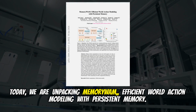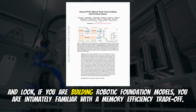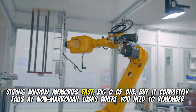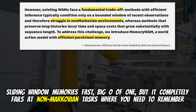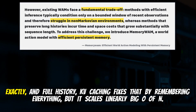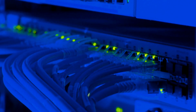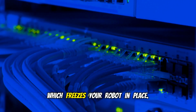Today we are unpacking MemoryWAM: efficient world action modeling with persistent memory. And look, if you are building robotic foundation models, you are intimately familiar with the memory efficiency trade-off. Sliding window memory is fast, big O of 1, but it completely fails at non-Markovian tasks where you need to remember past states. Right, because those states are not visible anymore. Exactly, and full history KV caching fixes that by remembering everything, but it scales linearly, big O of n. So your latency and GPU memory requirements just absolutely explode. Which freezes your robot in place.